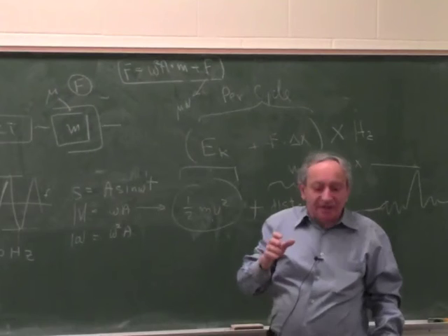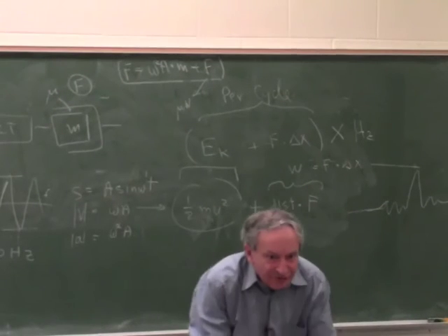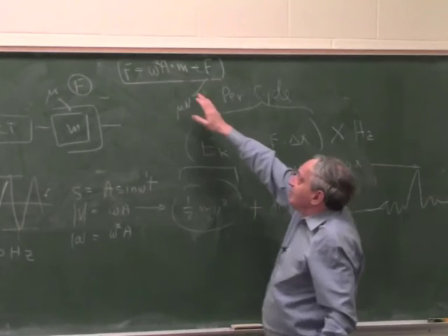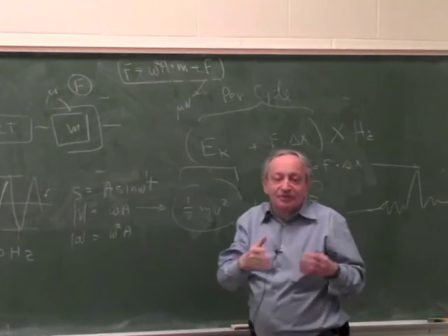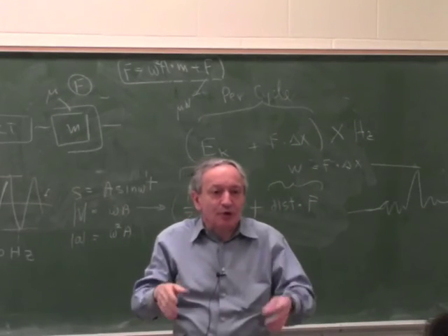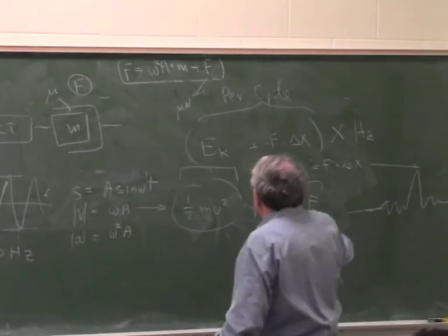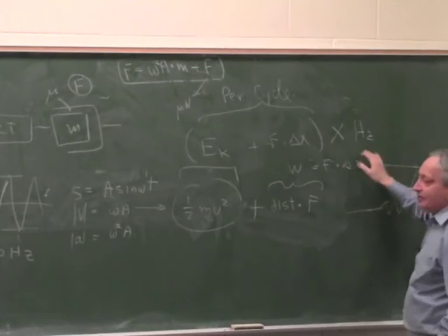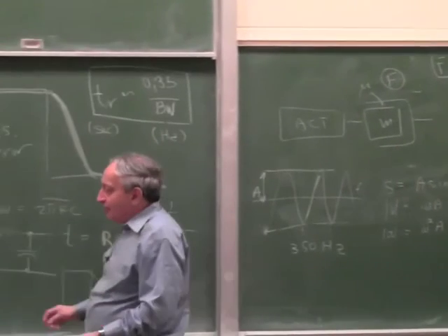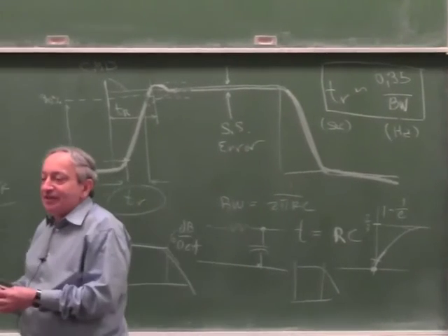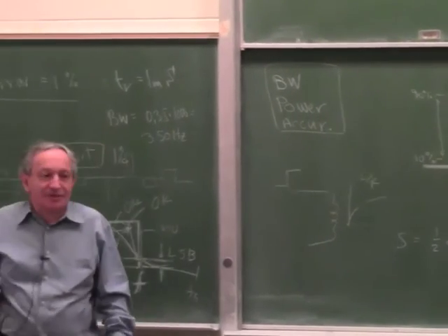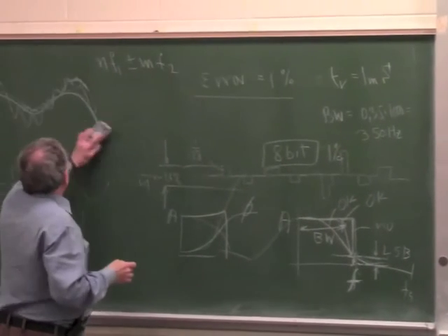So if the actuator is limited by force, if that's a weakness, it's easier to do it this way. Calculate the peak force, compare it to the data sheet of the actuator. If you're more worried about energy, say the motor getting too hot, then you should calculate the energy per cycle times the hertz. Now, the usual pitfall whenever you calculate heating of something is that people use the average instead of the RMS, and we went through it enough times that I don't think you need to be reminded.